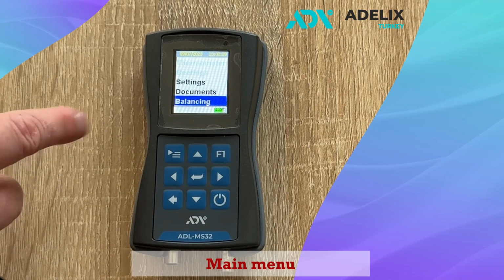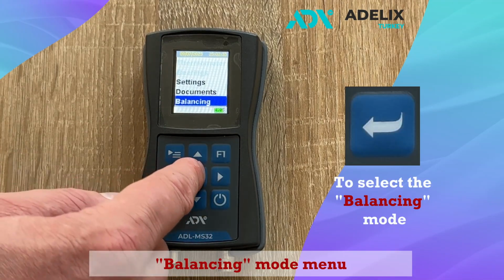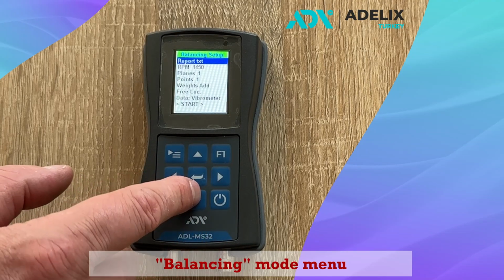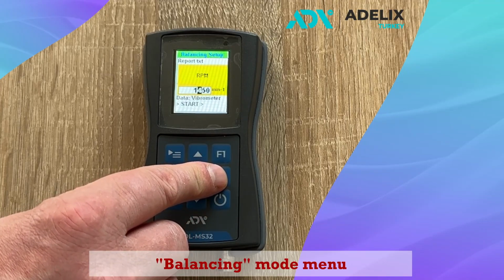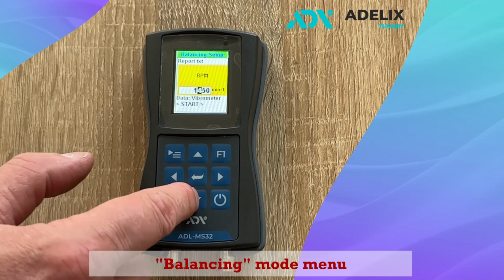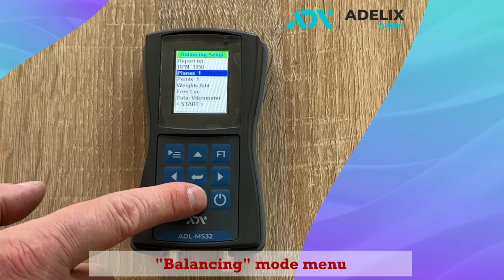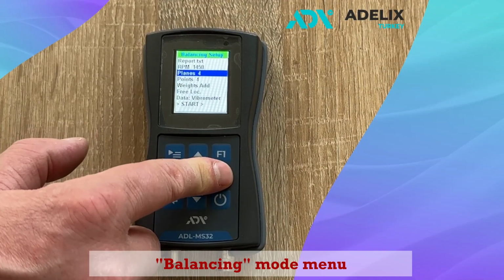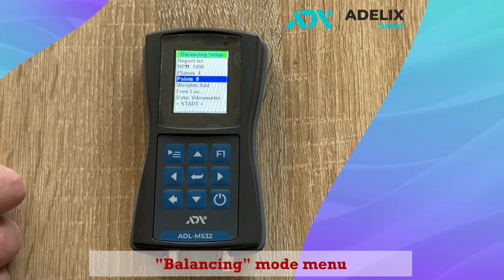Next, we select the Balancing mode by confirming it with the button. In this mode, you can save the report, set the rotation speed, choose the number of balancing planes, up to 4 correction planes, the number of control points, up to 8 control points.